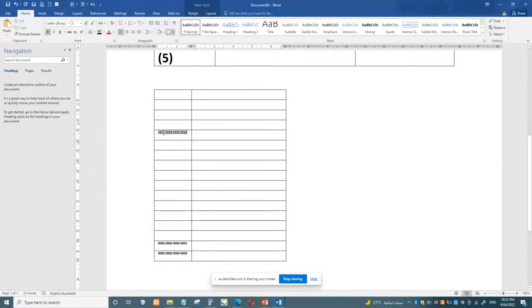Now, if you need to spend all 16 bits for referring to the address of one memory location, what about your other operand? So you cannot do that, but you can refer to this memory location where you need only 8 bits, because the remaining bits are 0, so you don't need to be worried about that. So this memory location you can easily refer using 8 bits.